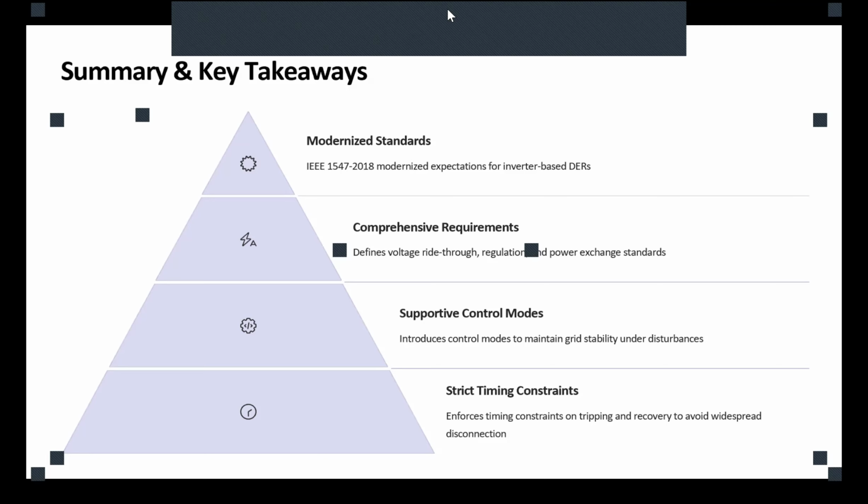Now, when the fault is cleared, meaning there is no malfunction or disturbance in our system, the system could go back to its previous normal steady state situation. But we don't go instantly, because if we go instantly, it would also be considered by the system as another fault or another overvoltage. Do you see what I'm saying?